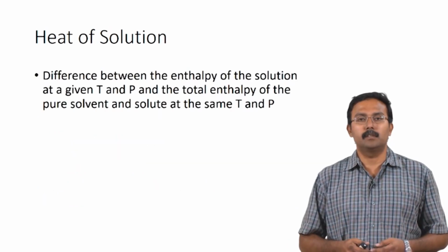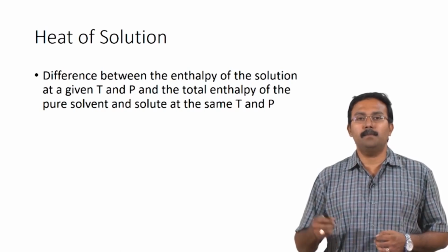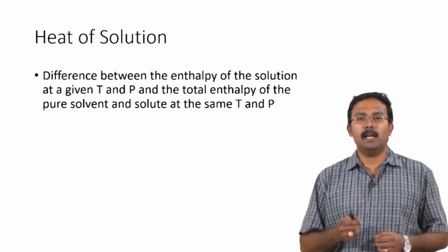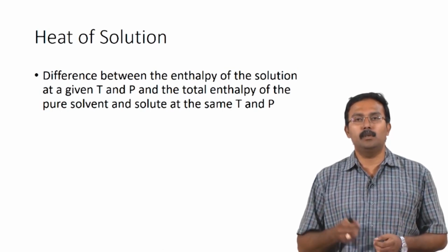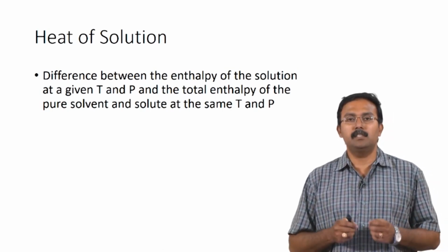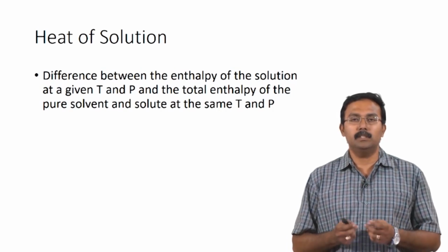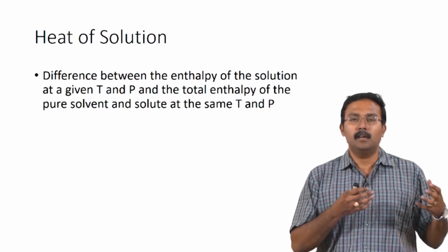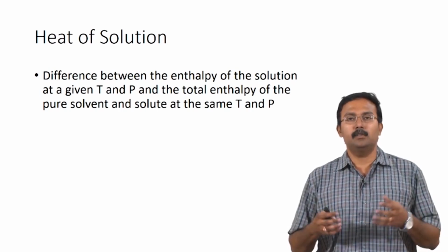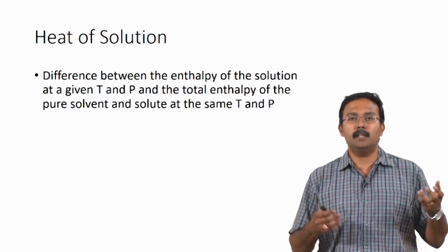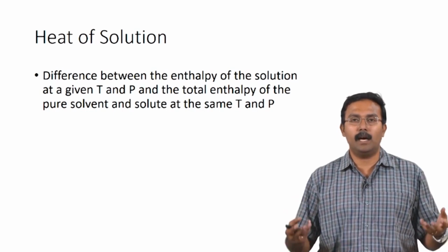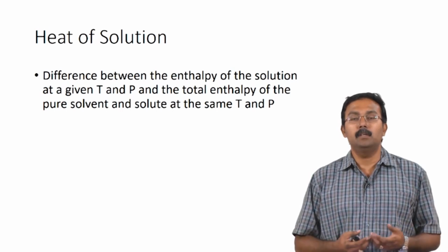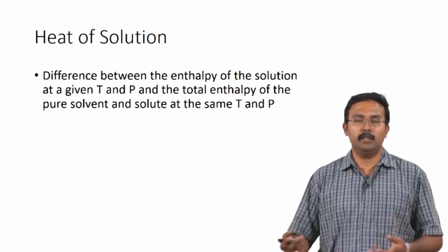What is heat of solution? The difference between the enthalpy of the solution at a given temperature and pressure and the total enthalpy of the pure solvent and the solute at the same temperature and pressure is defined as the heat of solution. So, this is quite simple. Think of this as having an initial and final condition. The initial condition is where the pure solvent and the solute are existing separately at a particular temperature and pressure. The final condition is the solution which is formed.